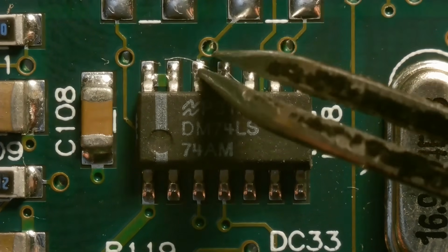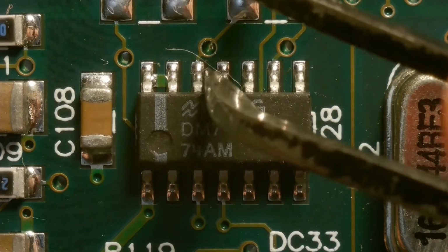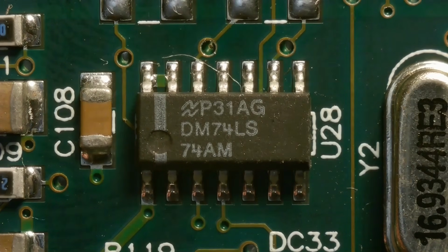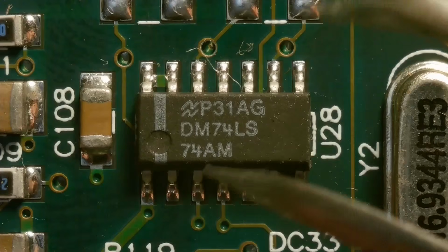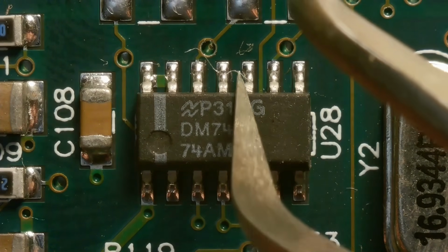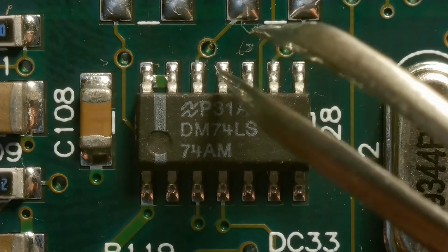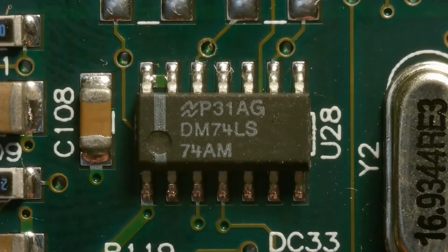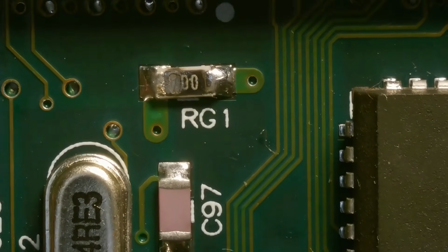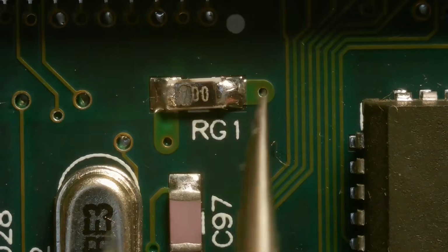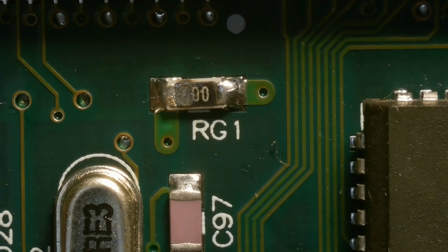I checked the area around under the microscope once again and found some suspicious spots. First of all, this hair or something on the 74LS74 IC, which got so hot, looks like it's in the solder and was shorting 2 pins. Maybe it is some leftover from a thin wire which was burned in here, I don't know. Also nearby another burnt 0 ohm resistor from the ground. This one looks bad but seems still to be conductive. Just looks like a lot of current went through it.